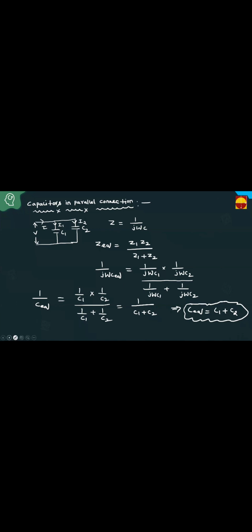Then similarly, how do we apply this? What is I1? Again, no need of derivation; directly, capacitors in parallel are similar to resistors in series. That's why we take the same capacitor, C1 plus C2. If it's a resistor, you take R2; if it's a capacitor, C. What is I2, students? I into C2 by C1 plus C2.